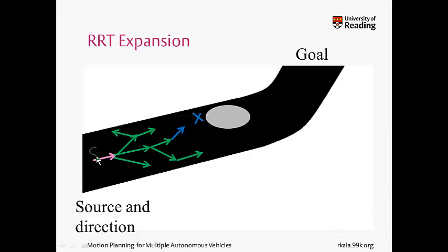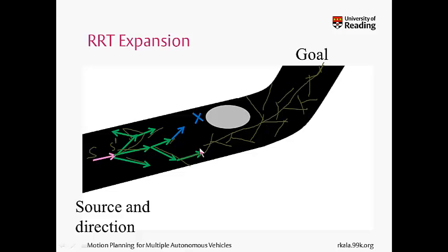This was the vehicle source. This was the current heading angle. This becomes the effective source, after which I completely randomly generate points. I randomly grow my RRT like this, and ultimately this kind of exploration in and around will reach the goal, and this will become the trajectory to be traced. So I can solve this problem. The first part of the problem is almost solved in this mechanism.